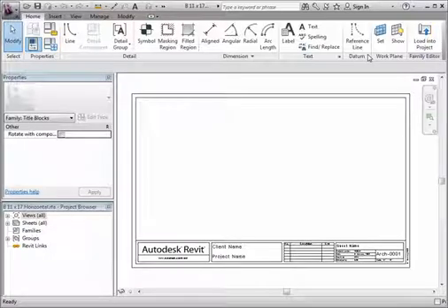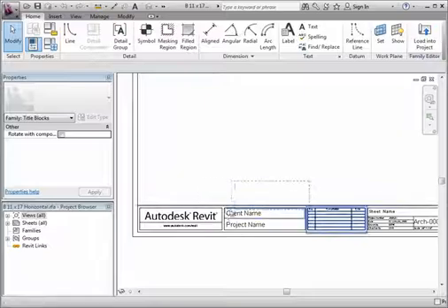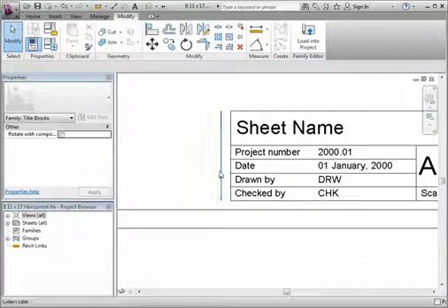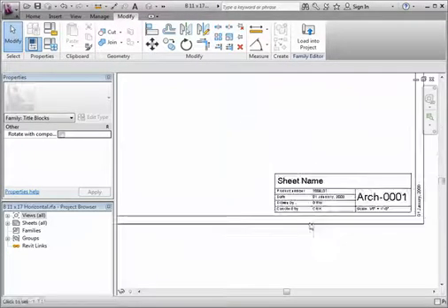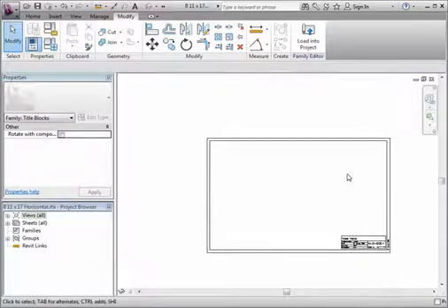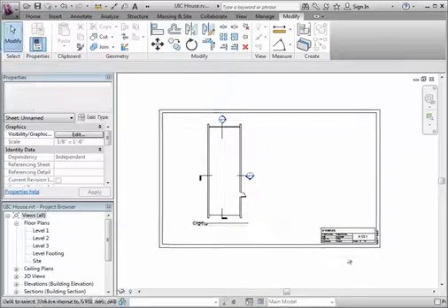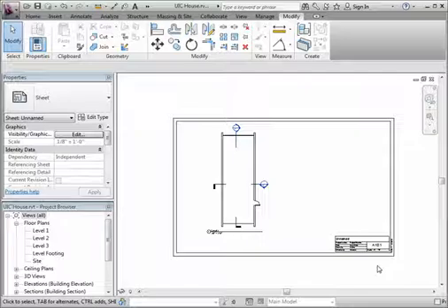It's all by itself. And I can edit it here, and then I can save it out as its own family file, just for my own records. And then I can actually load it back into the project, and it'll update it. So I don't really need any of this stuff. Let's just say for now, that's fine. And that we can load this back into the project, and it will overwrite the existing version, and it'll be a little bit simpler. Okay?